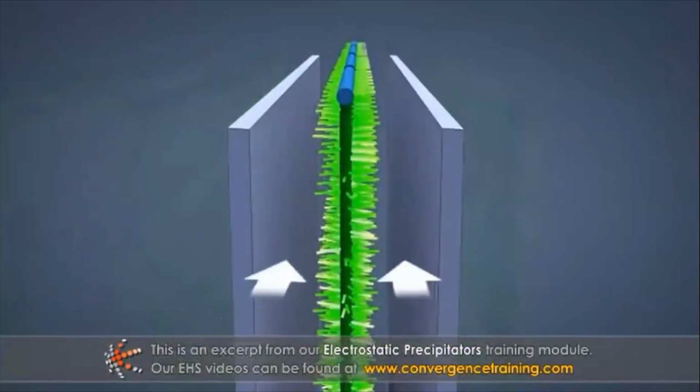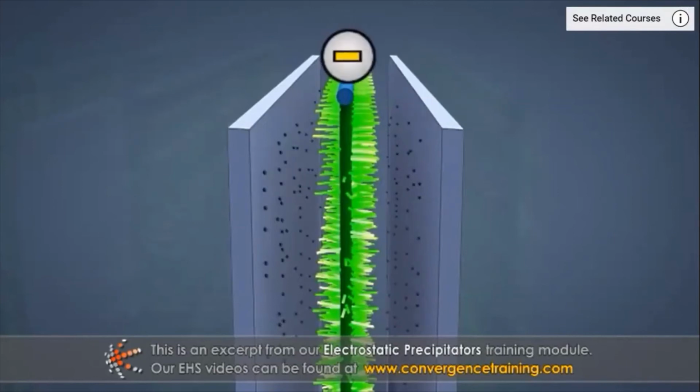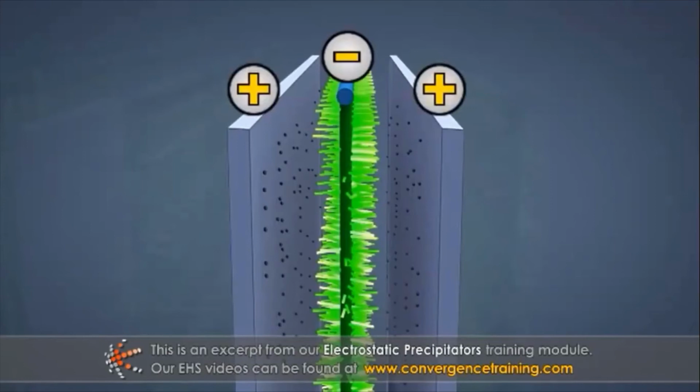As flue gas flows through the chamber, dust particles and other entrained flue gas components pass through the high-energy field and become ionized. This drives negatively charged ions and particles to the collection plates. The particulate matter builds up on the collection plates and forms a layer.